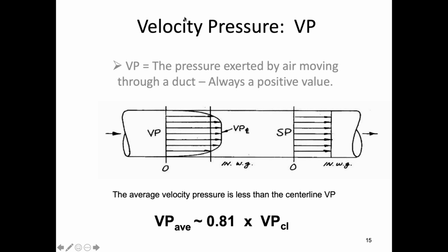And this Pitot tube, what this is doing is that there's a little opening over here, and air, as it's coming in here, it's blowing against this Pitot tube, and it's connected to a gauge that'll measure the pressure, something called a manometer, right? So if I blow air in here and I measure it over here, am I measuring static pressure or velocity pressure?